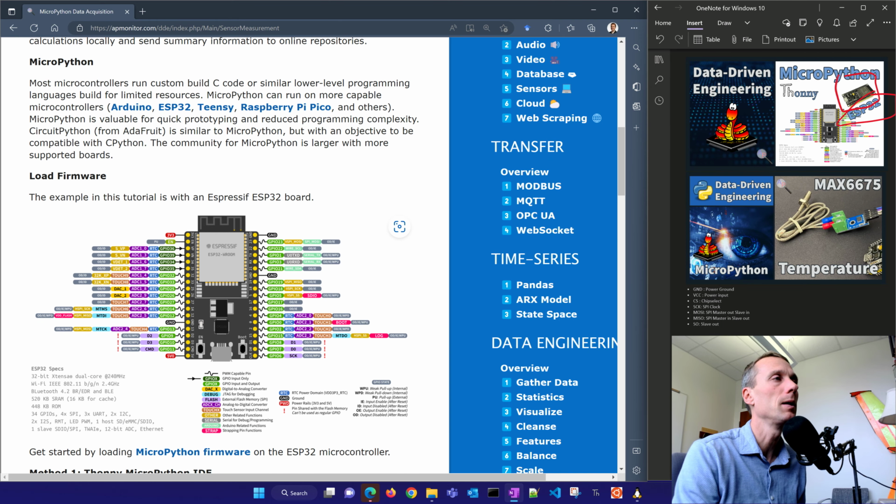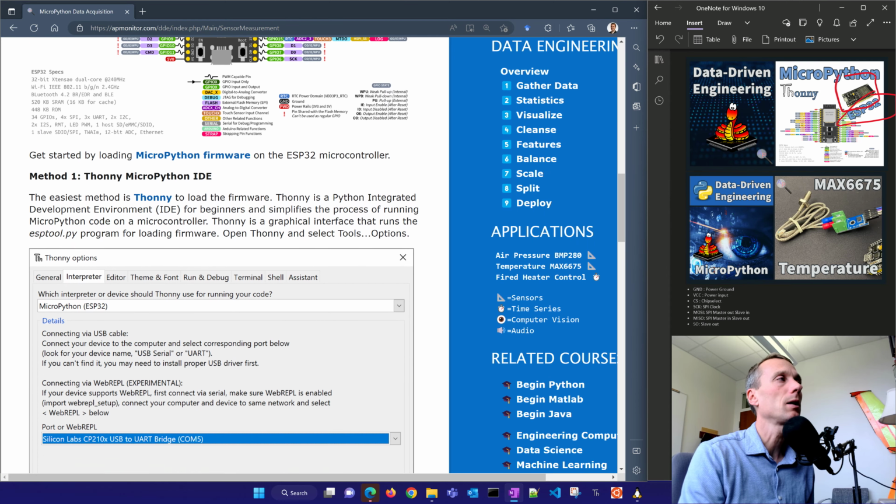Okay, so you want to have the pinout here, schematic. That'll help you show what types of sensors you can attach and where you can attach them. The GPIOs, general purpose input output, those are the ones that we're going to typically use, but they're going to have things like the SPI SCK, our serial clock there, the master in, slave out, master out, slave in. So these pins have multiple purposes, and we can configure them certain ways depending on the sensor that we want.